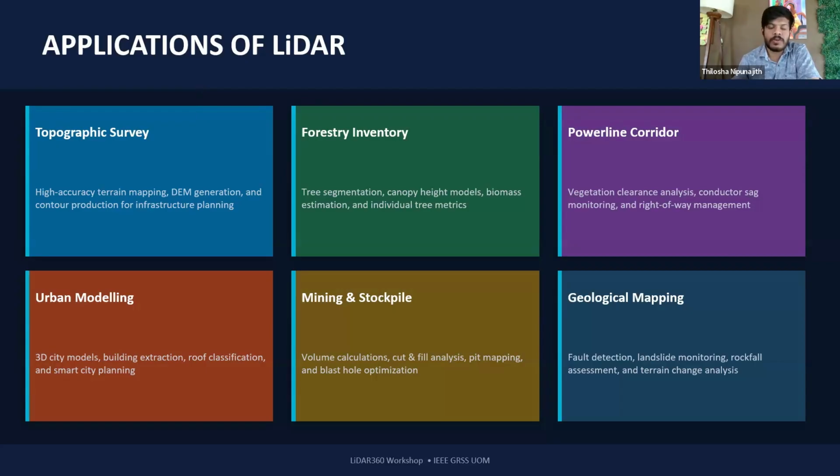Most of the time you think LiDAR is all about 3D point cloud and deriving 3D data and 3D modeling, but it's not like that. If we have a proper high densified point cloud that reaches within our accuracy limit, we can derive raster data using this kind of point cloud as well. It's quite handy: suppose you are doing a survey in a very crowded area, like a city model, and you need to understand how the ground features have been established in this city area.